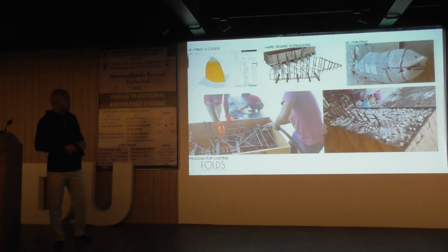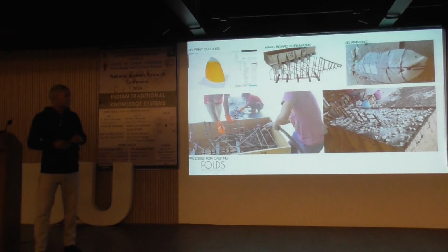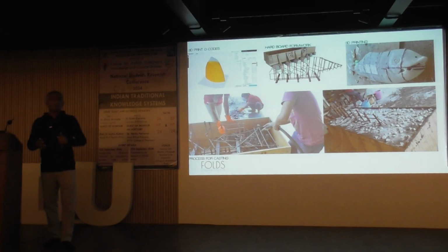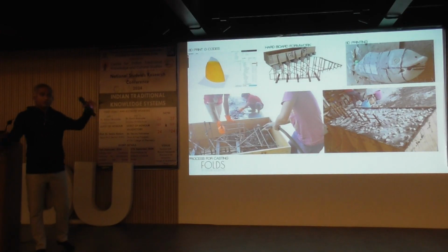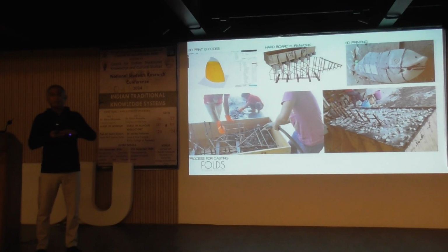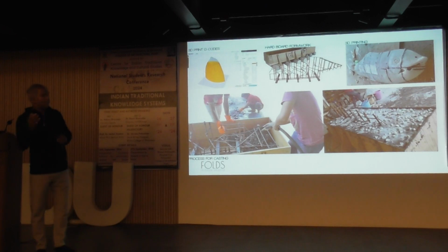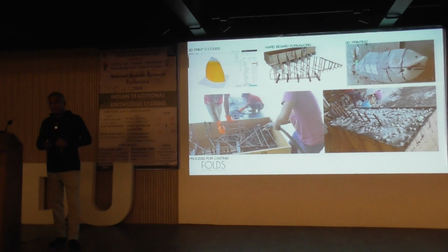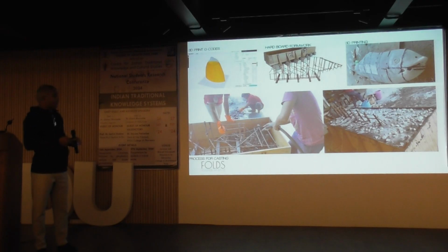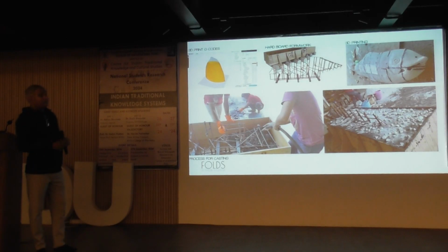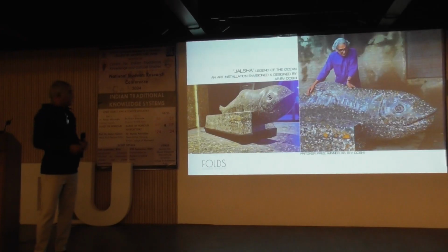We built it using 3D print technology at that given period of time, getting the skeleton of the fish inside it with the reinforcement and the structural thing happening. For the first time, we were casting composite marble in a huge block format. Usually composite marble can be cast only up to 10 to 20 mm thick, because of the heat, there might be a lot of cracks. This was the first time we were doing it in solid format. Fortunately, we achieved this in such a way that layering was done over multiple time periods, so that there are no breakages, no cracks. So finally we could achieve that.